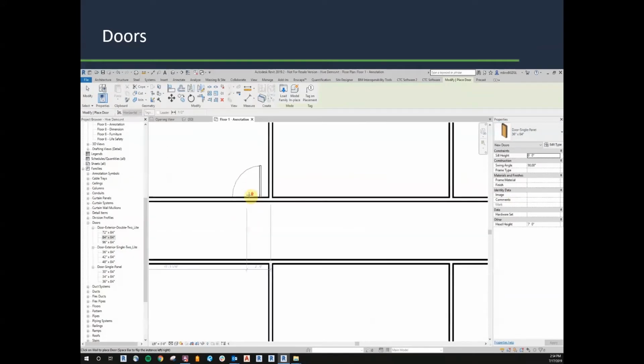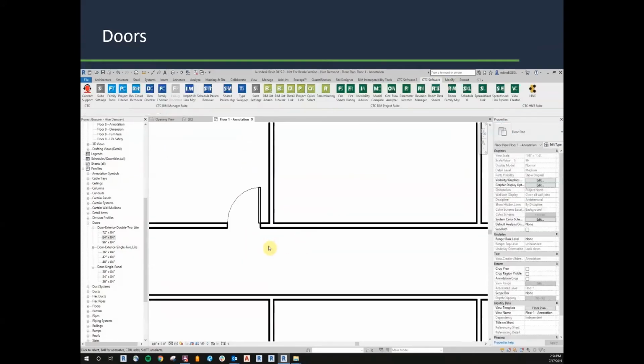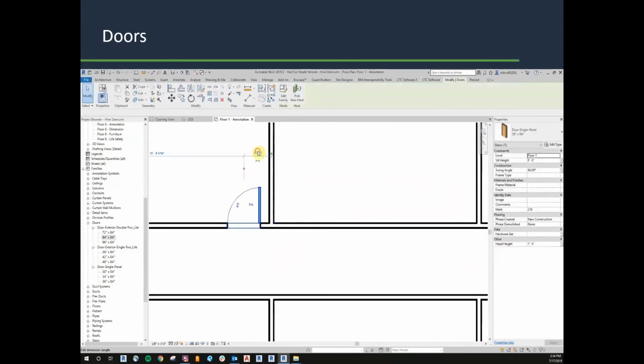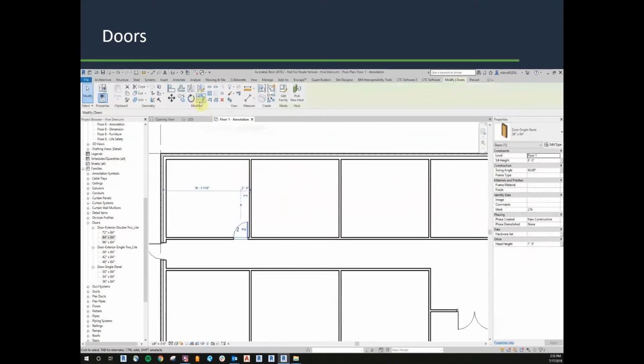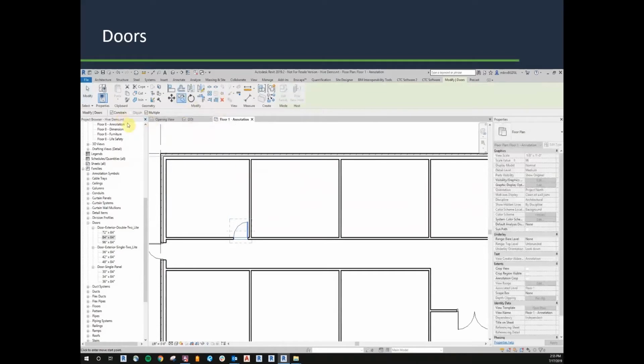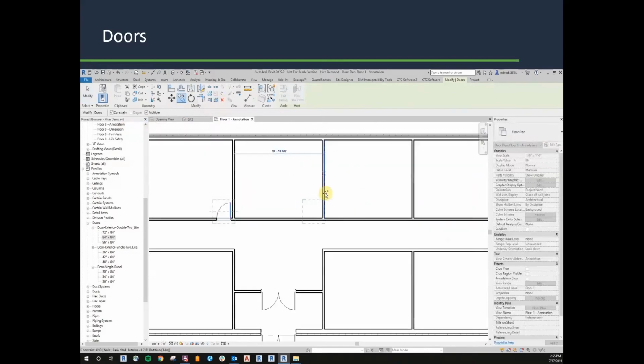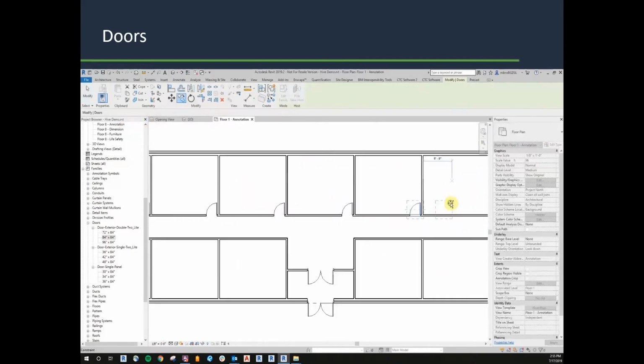Okay, and we'll change it one more time and we'll insert our typical interior doors as single doors. Place this guy. And normally I would nudge to move the doors around, but you can select the temporary dimension and change it to move it closer. Or you can select it, move it closer still. And from here, I'll just copy it around to the other rooms, multiple, constrained. And we'll go wall to wall.